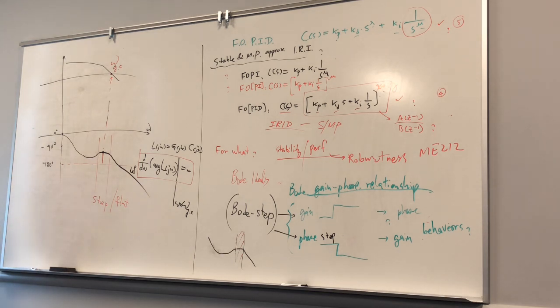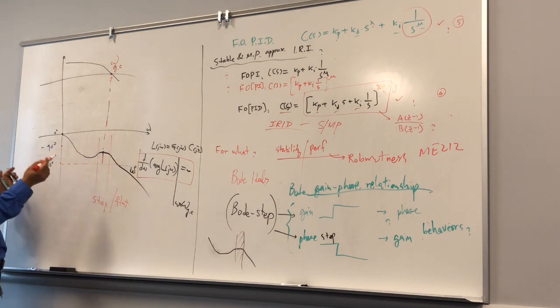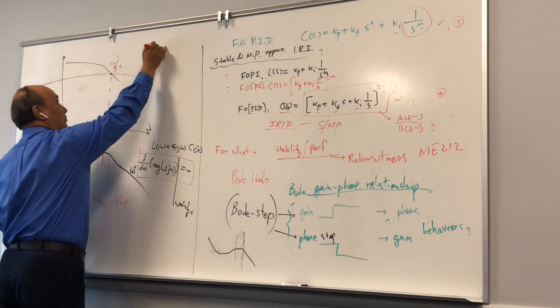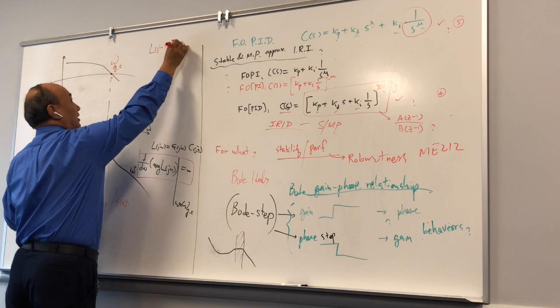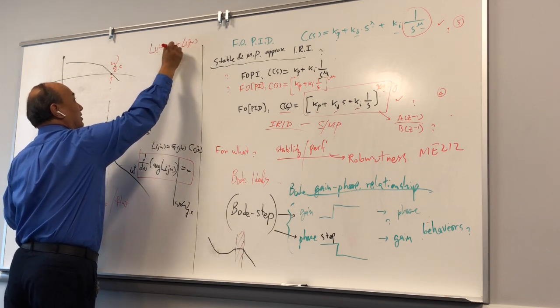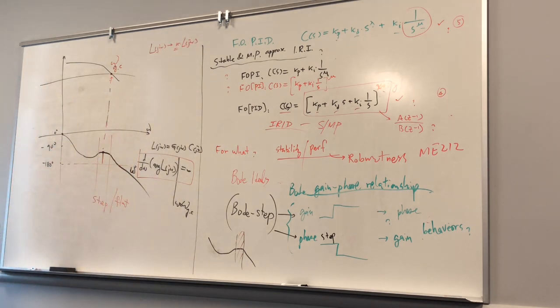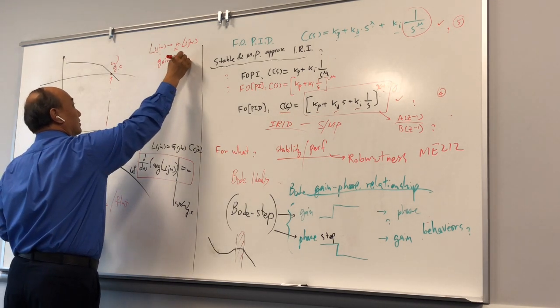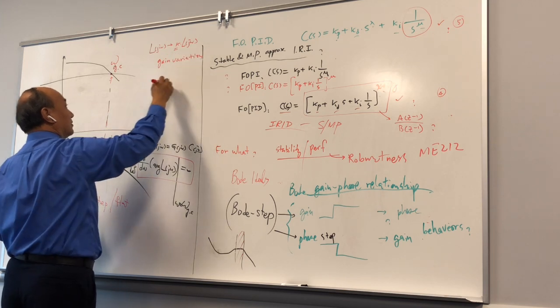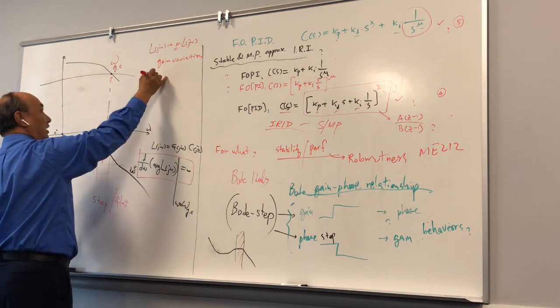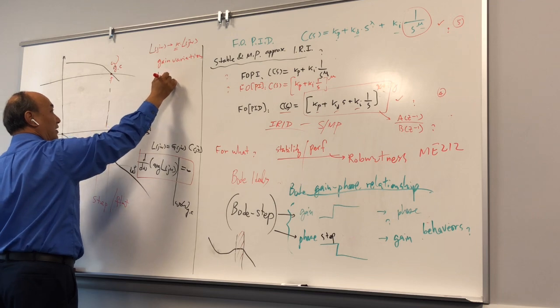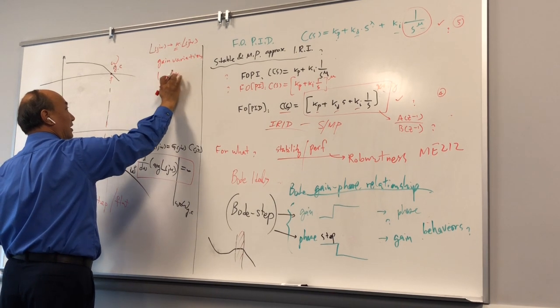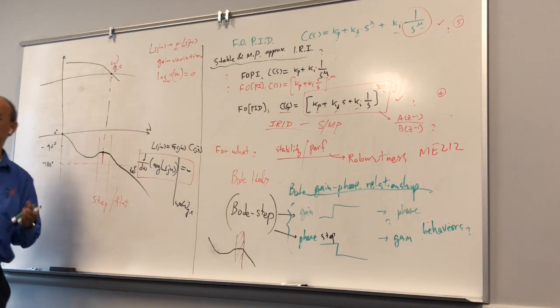So why is the flat phase condition important? Because if you have some system where L(jω) becomes K times L(jω), where K is called the gain variation. If you take log, usually log 10 K is 0 dB, right?